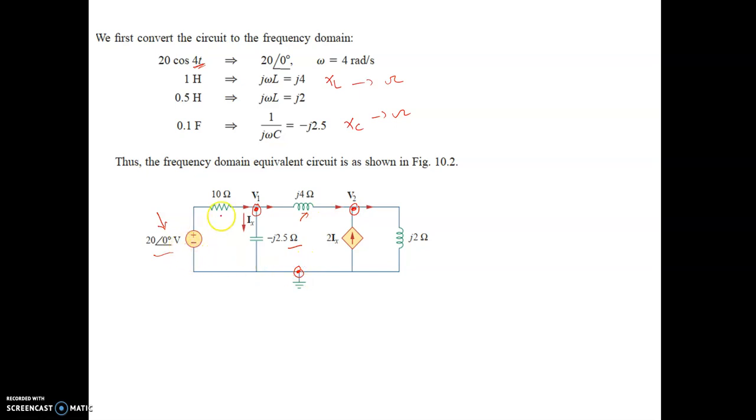This voltage source is connected across node 1 and the reference node, so we can solve this problem without using a supernode. If the voltage source were connected across node 1 and 2, then we would have to use a supernode. There are two non-reference nodes, so we have to formulate two equations with respect to these two nodes.